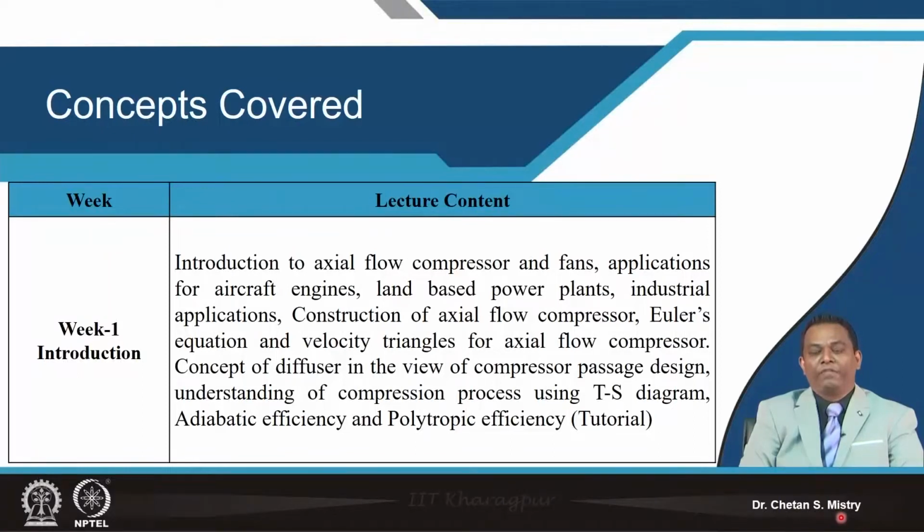Now with this detail we moved forward by using our fundamental equation, that's what is called Euler's equation. We discussed various velocity components and their uses. Then, most importantly, we correlated the diffuser or diffusing section with the flow passage within the axial flow compressor blades.